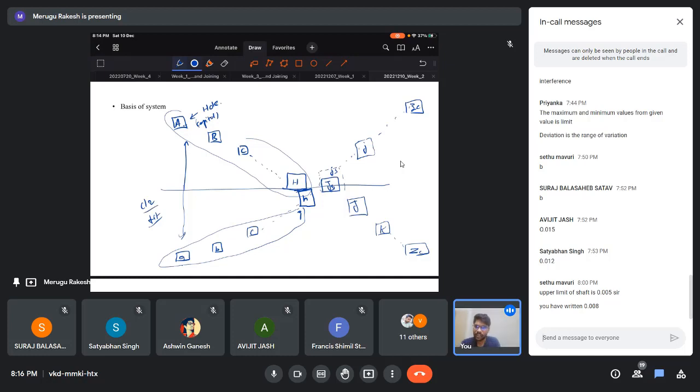If there is any question saying capital A and small a, you can directly go for clearance fit. Every time it has a clearance fit, and after this you have an interference fit, because this shaft is every time higher than the maximum material limit of the hole.